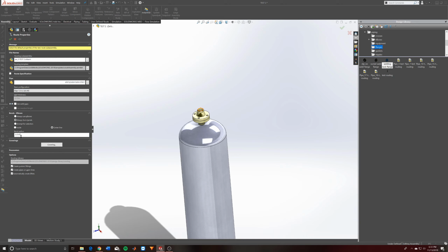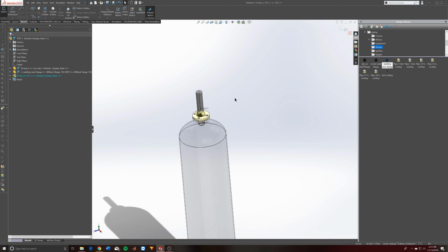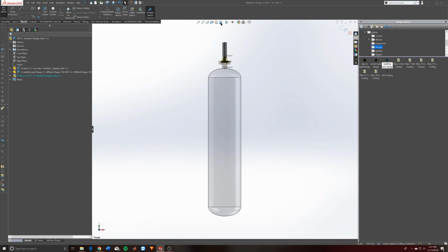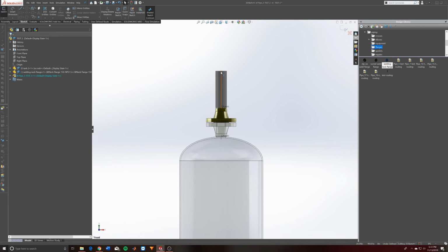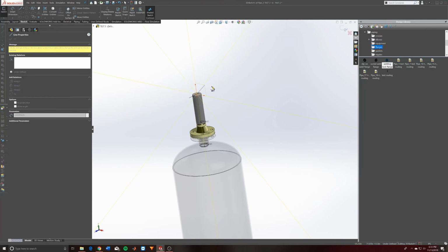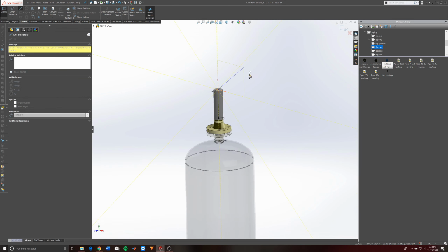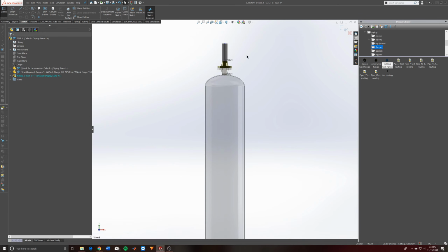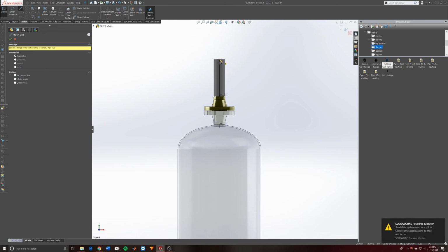But for now, this defines bend radius and a bunch of other things. Usually the default sets are pretty good, so just go with those and hit OK. From here, what I would highly recommend is that you enter a certain plane that you're going to draw off of. I'm just going to use the front. The reason is because whenever you use a line, it's actually going to be a 3D sketch, and if you aren't on a certain plane, it might make it difficult to know exactly where you are. So to make things easy, just stick to a plane and use that to draw.